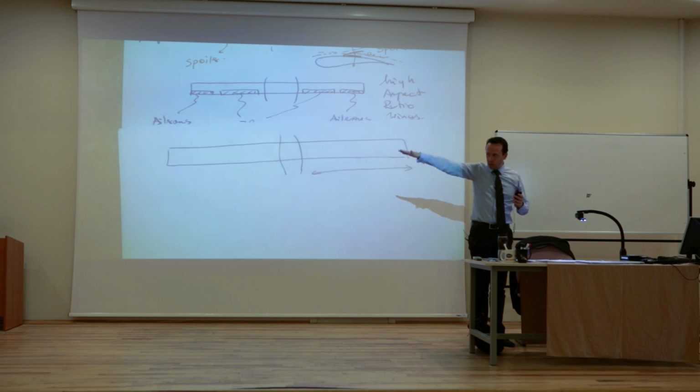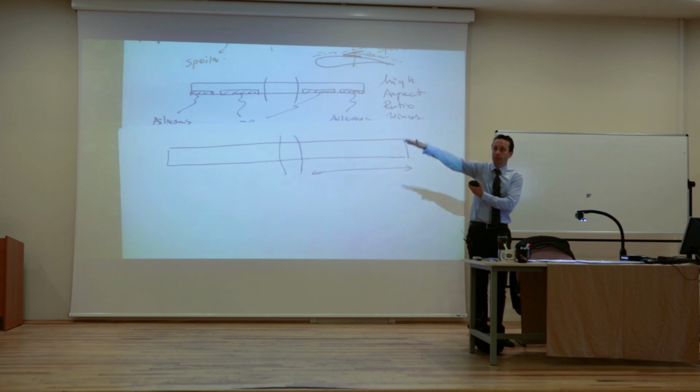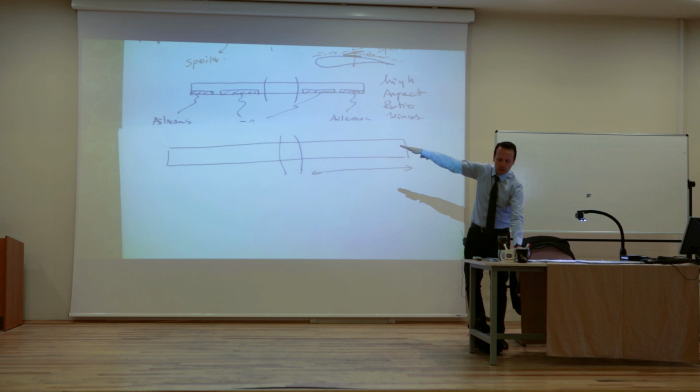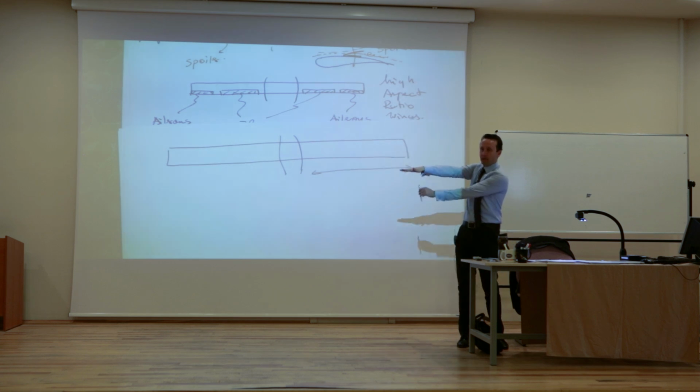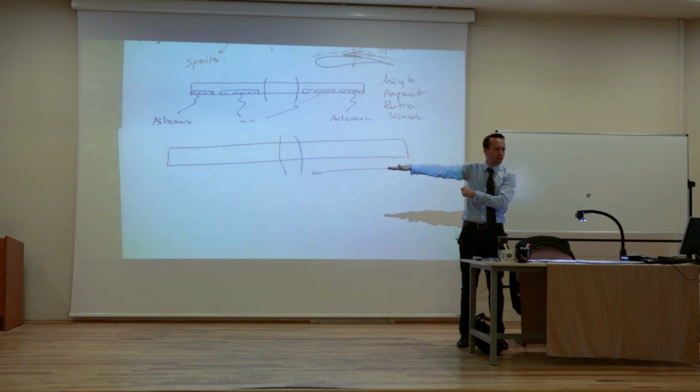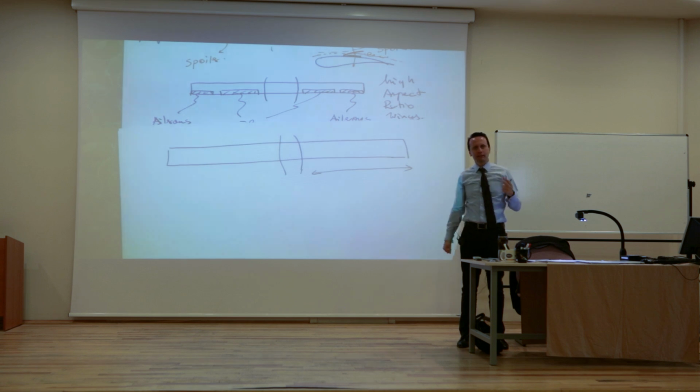When it's going down, it increases the angle of attack. When it goes up, it reduces the angle of attack. Because when it's going down, you have a relative wind coming from here now, right? Do you understand that? So when it oscillates, it changes the angle of attack. The angle of attack actually starts changing because of that movement. And the airflow is not necessarily steady at that point because it's moving a lot, so it becomes unsteady.